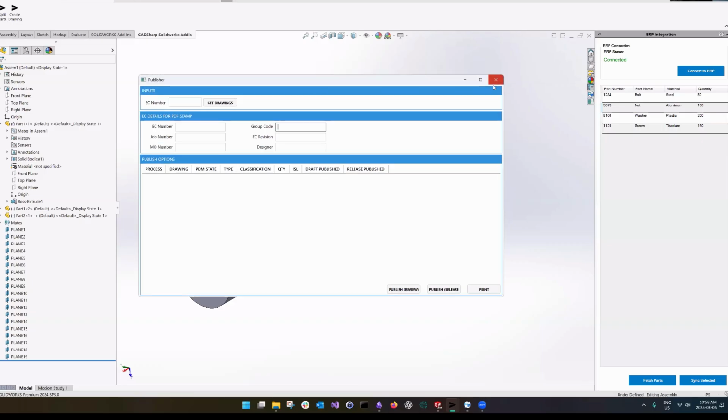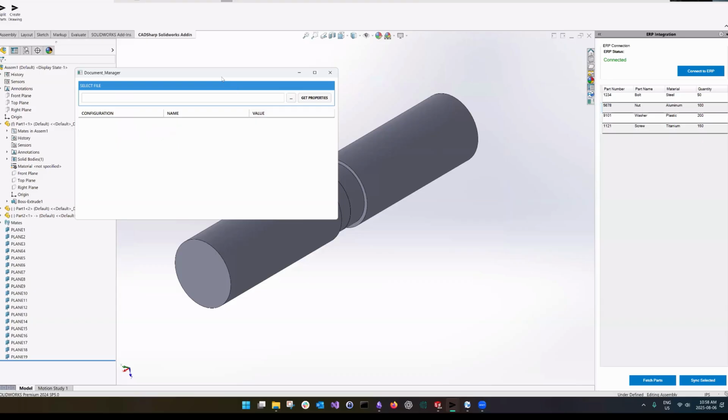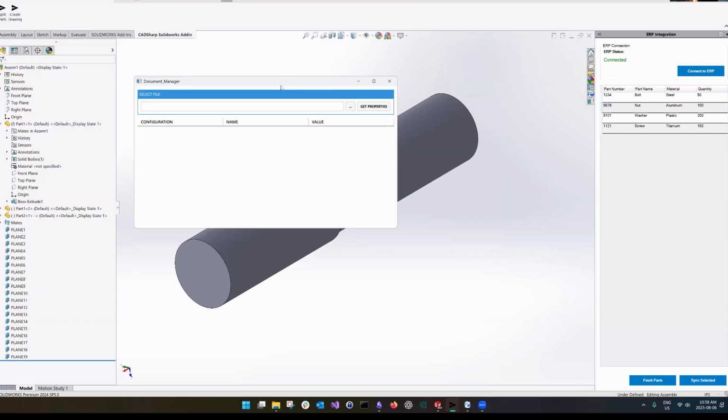All right, one more example I have for you. This one's worth paying attention to. I want to talk about the Document Manager API. This is a separate API provided by SOLIDWORKS. You need a key for it. It's a company-specific key. It's free as long as you have an active subscription of SOLIDWORKS. If that's the case, there's a form you have to fill out and send to SOLIDWORKS. And if you have an active subscription, I've never seen one get declined, and then they send you the key. That key allows me, again, we have an internal one for development, but for use, you need your own, to read SOLIDWORKS files and write to some extent without opening.